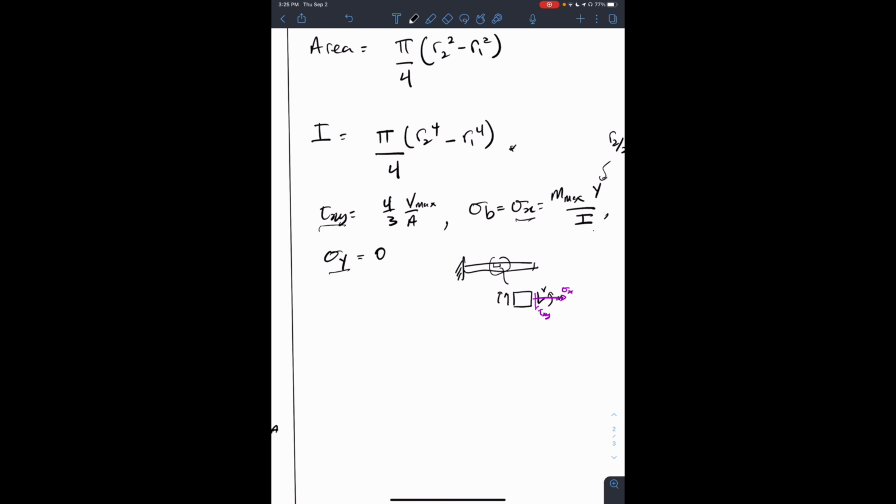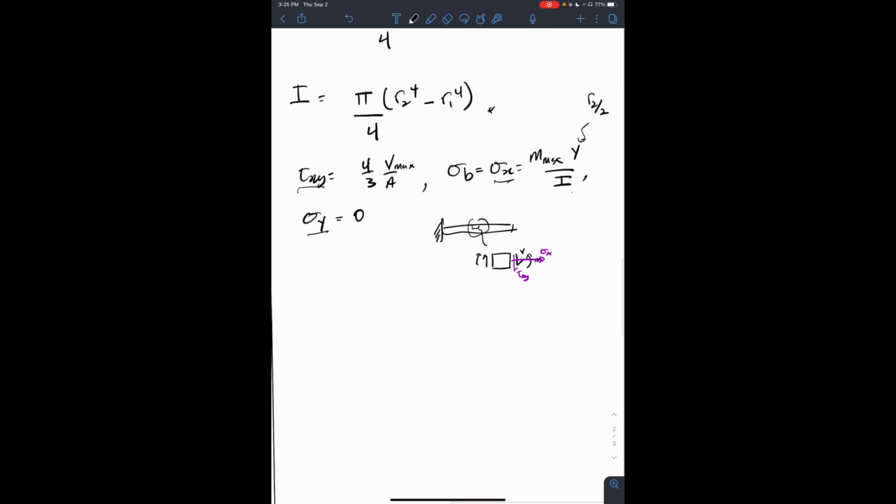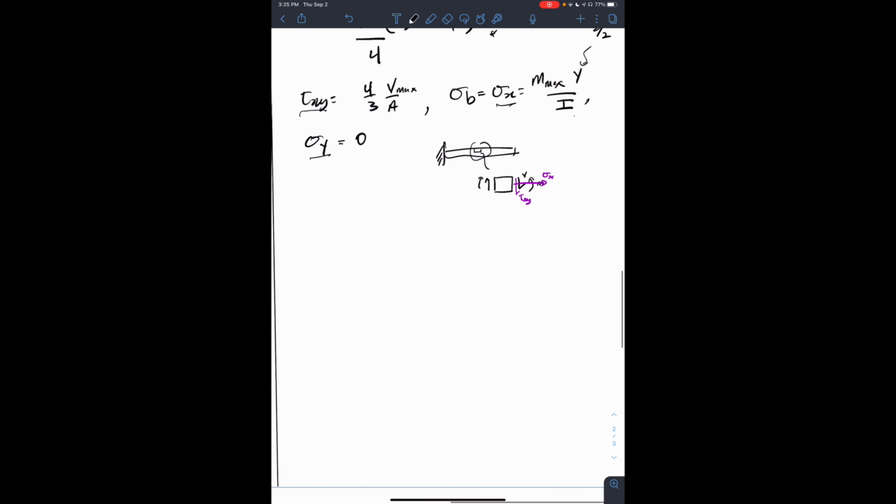The next thing we're looking at here now is combining stress states. And you will have done this in strengths when you did Mohr circle. So this formula, tau max I should say, not tau xy, is equal to a half of the formula you could recall, which was the radius of your Mohr circle.